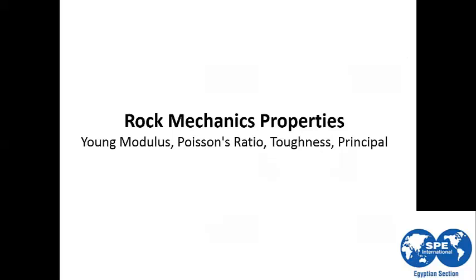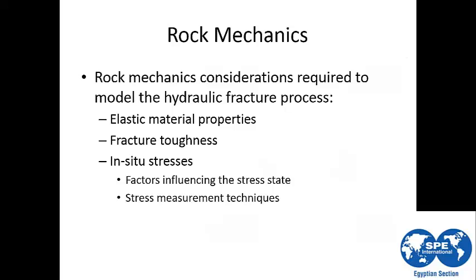So we will start now with the first part of our course, the rock mechanics properties. We will discuss in this topic the Young's modulus, Poisson ratio, fracture toughness, and in-situ stress. First of all, the rock mechanics consideration is required to model the hydraulic fracturing process, because it affects all the important parameters and the fracture shape itself inside the rock.